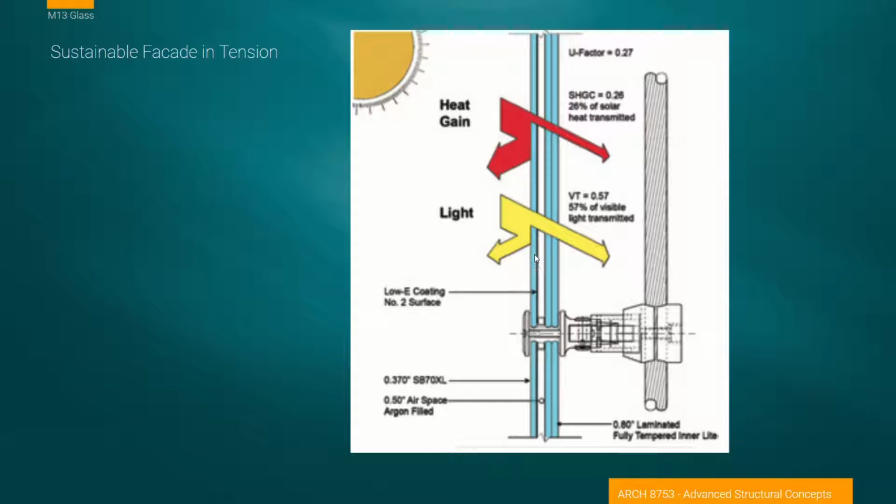There are also thoughts as to which surfaces are coated with these in order to control the visible appearance of the glass to the viewer. So you can change the way the building looks by where the coating surfaces are applied, where the tinting is, where the air spaces are in the glass, and the type of glass that's used.